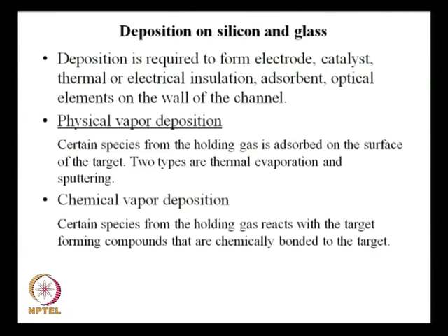So, we have already discussed how to do the etching. We have a process which goes by the name spin coating, which was used to coat the substrate by photoresist material. Then we have a mask aligner to set a mask on top of that. Then we have a light source, and we illuminate.